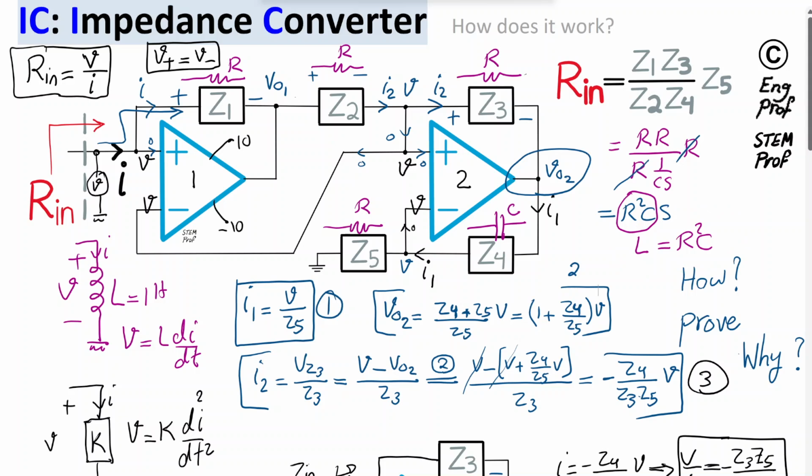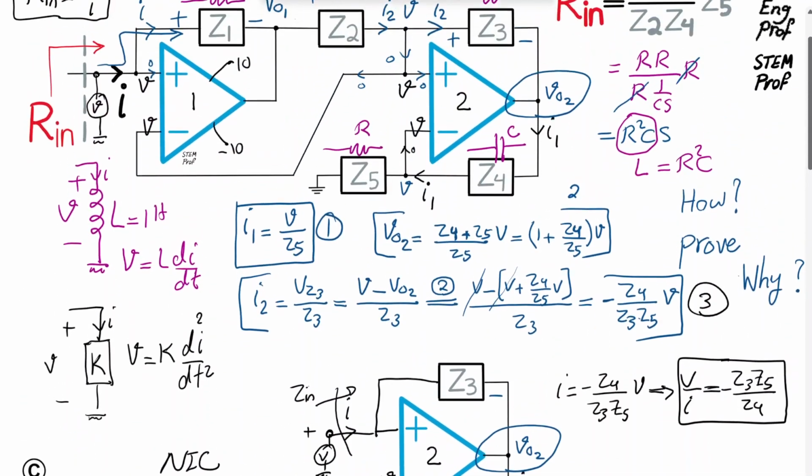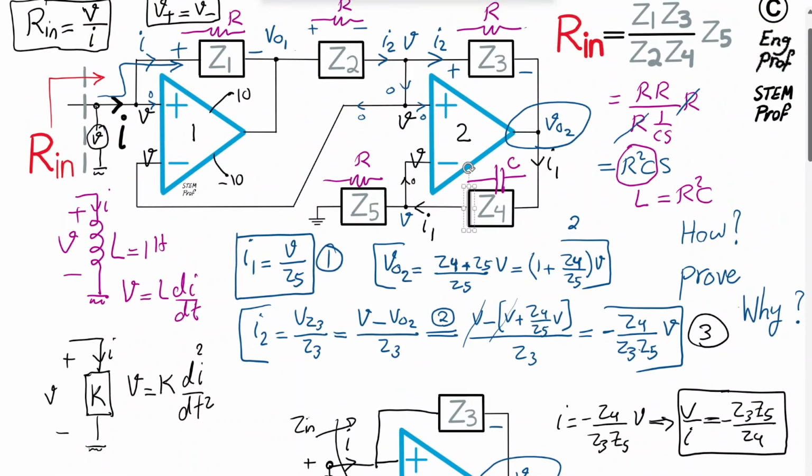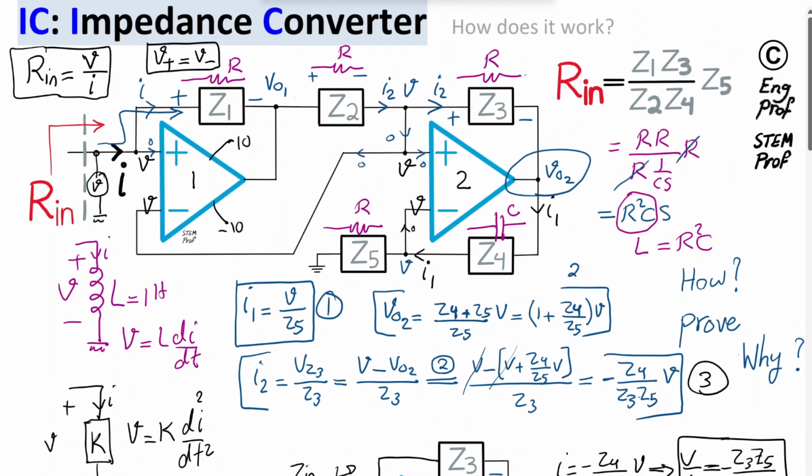Again, there are many possibilities, but I just wanted to highlight the power of the general impedance converter, and the fact that we will also be able to realize very interesting scenarios, like, for example, the second derivative, or the kind of component that computes the second derivative of the current and then reports it as the voltage across the component. So that's also an interesting thing we can realize. You can even think of a weird scenario where we compute or report the third derivative, whether that's a practical or stable scenario is a different thing.